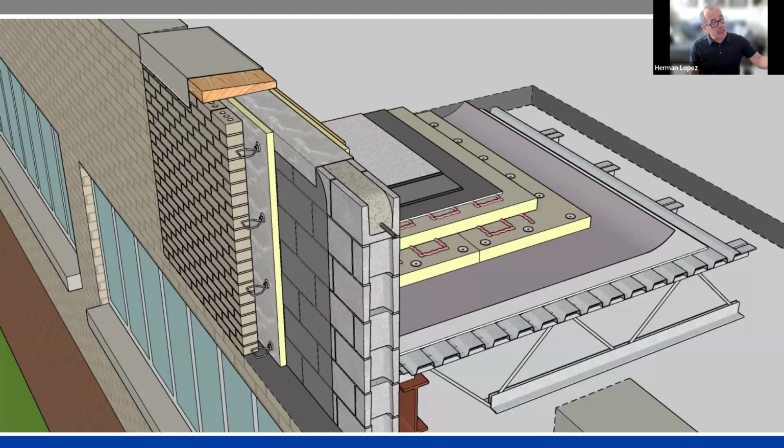So as we come over the top, we've got some parapet cap there. We've got our wood coping and then our cap flashing, but we continue a wall on the other side. And so again, we're going to add some insulation, and we're going to bring a roofing membrane up to it. But the concern here is that we now have unconditioned air on both sides of it. It's going to be hotter or colder than the inside of the building, yet this wall is connected to all of that.